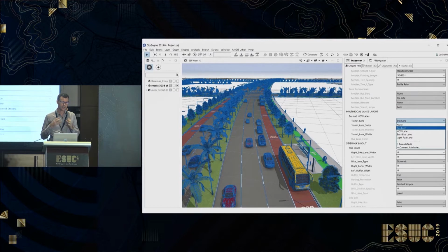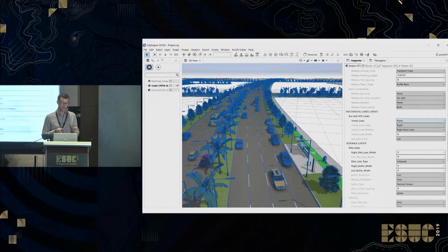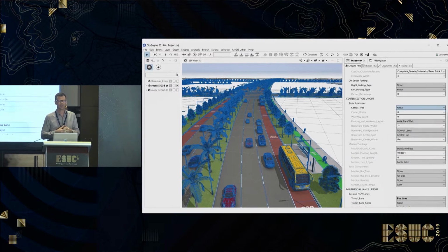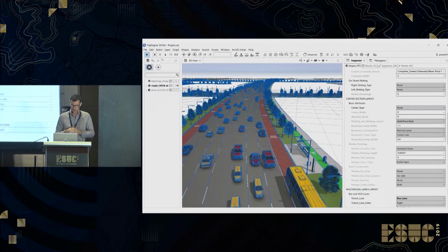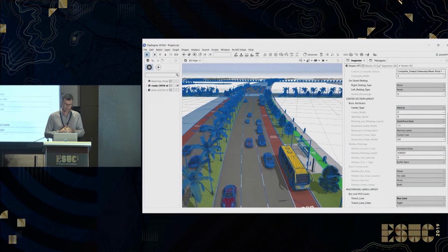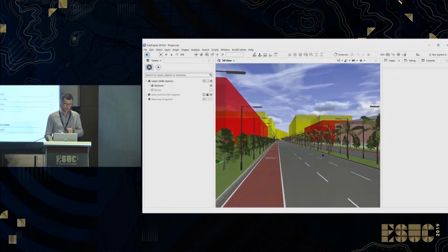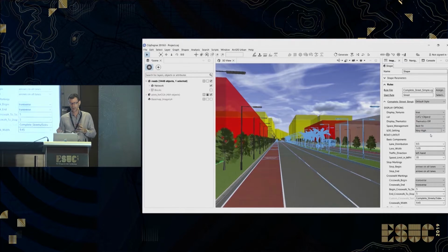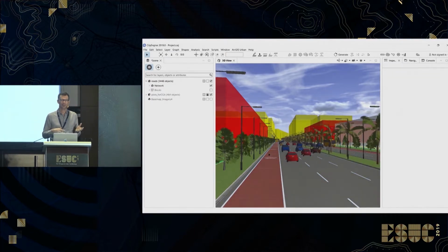So this allows us then to create the streets for these estates which match the LTA guidelines, and we can change and edit all the lanes of the streets and the trees and the setbacks, and all these parameters can be easily edited. We can also combine that with the 3D model that gets generated.